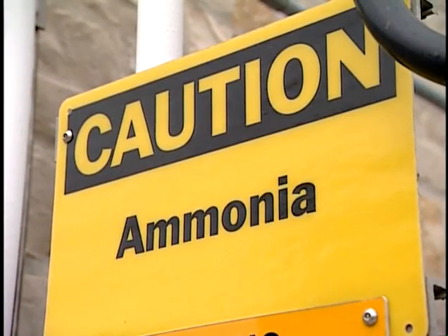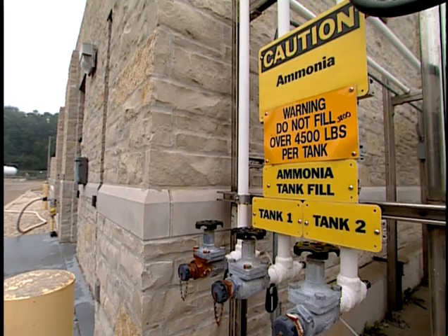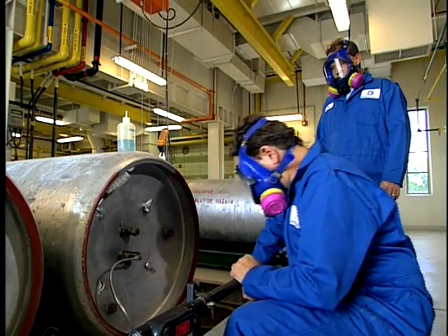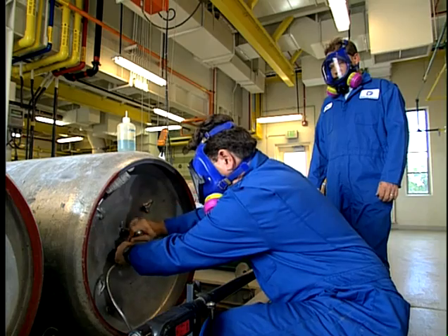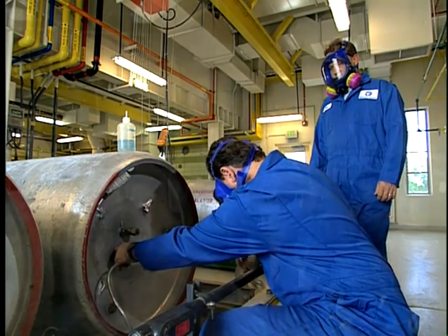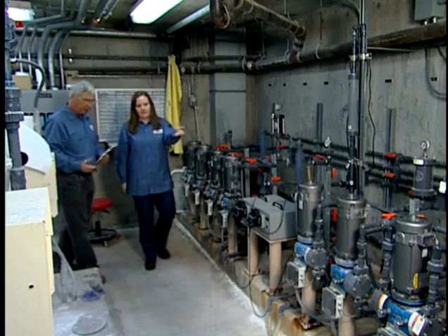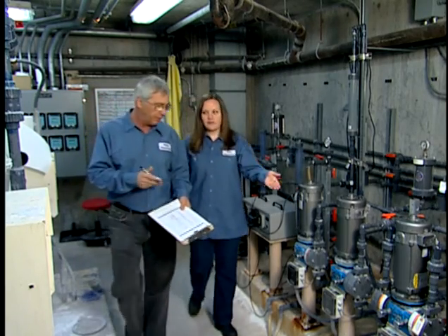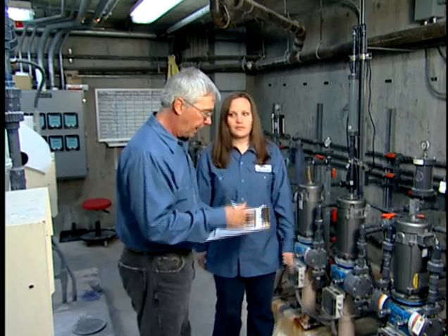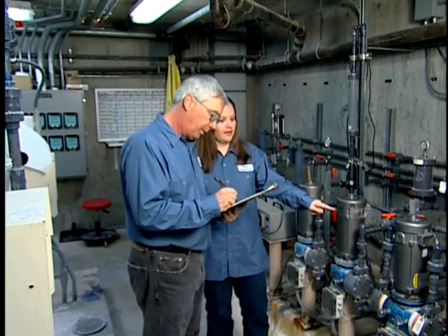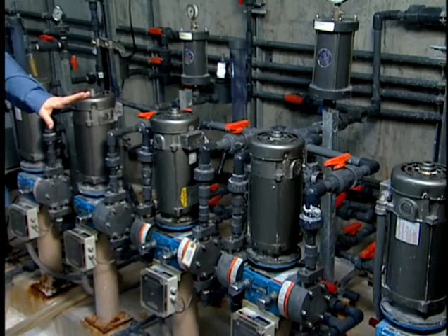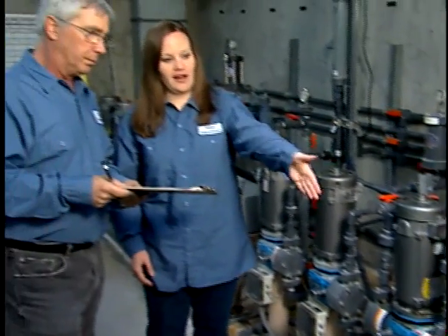The process hazard analysis is a thorough, orderly, systematic approach for identifying, evaluating, and controlling the hazards of processes involving highly hazardous chemicals. The process hazard analysis is best performed by a team with expertise in engineering and process operations. The team should include at least one employee who has experience with and knowledge of the process being evaluated. The team should also include a member of the utility's safety department or committee. A safety director provides valuable input and validates the PSM.